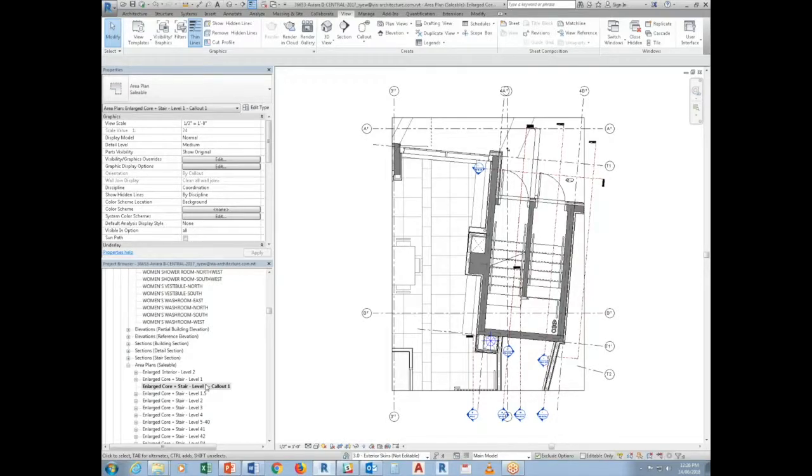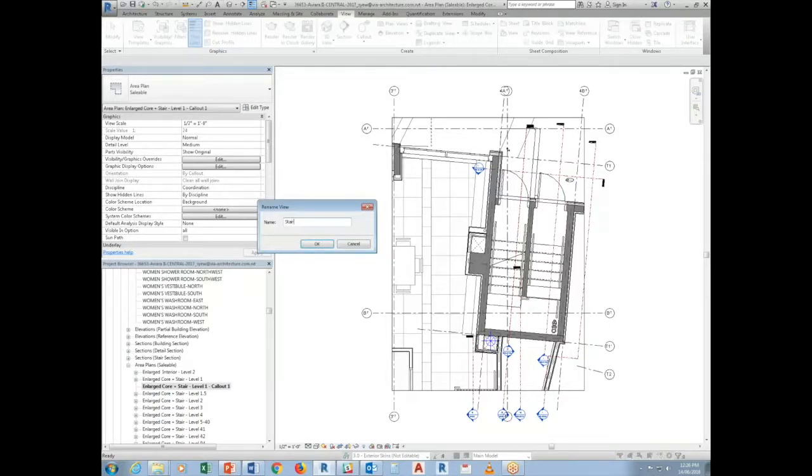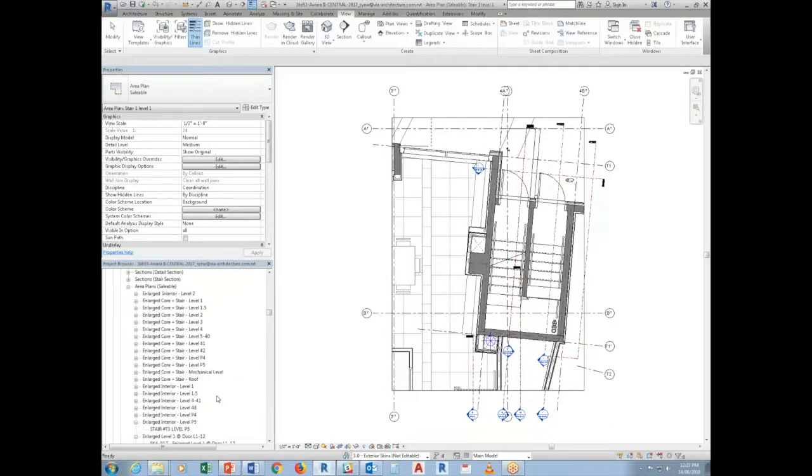Most of the time, people say this is going to be stair, level 1 or something, right? That's how people would do it with callout. But you don't even know if that thing is a callout or not. So every time people start renaming stuff, it's very difficult to keep track of that. This is why I just never use callout in a larger project.